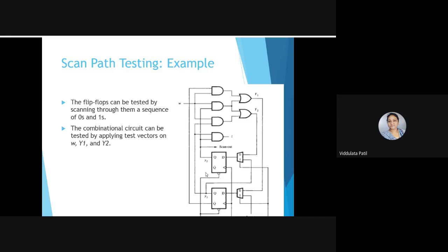So if we are going to test 4 test vectors, for each test vector we may require 5 clock cycles, that means a total of 20 clock cycles. But actually we are not going to use that many. For the first test vector there will be 5 clock cycles, and whenever the last scanning is going on, we load the next test vector.